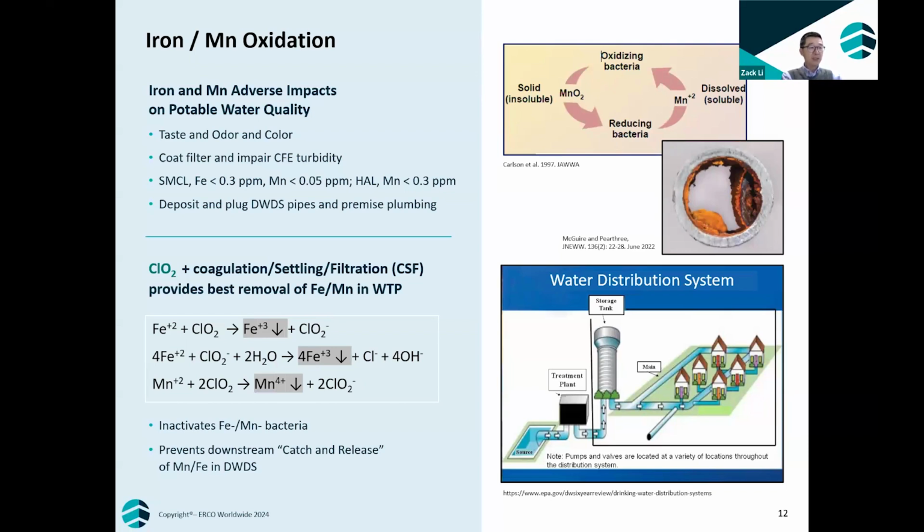Many US utilities use chlorine dioxide as a pre-oxidant to remove iron and manganese from the source waters. Iron and manganese can either be present all year round in some groundwater or be present seasonally in source water contamination. Increased iron and manganese content can cause rusty metal taste and odor and cause color in water. Iron and manganese are regulated by secondary MCL.